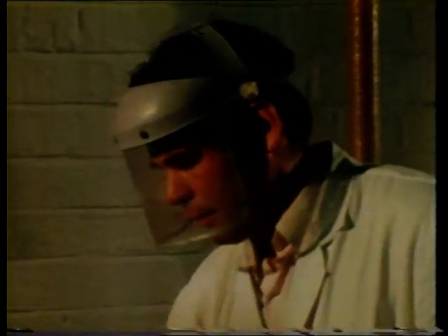First, we put into the molten aluminium a measured quantity of silicon. It's measured out by weight. After time, the silicon will dissolve. Then the magnesium can be added. We don't need anything like as much of this. Like the silicon, magnesium takes time to dissolve. This new material we've formed is called an alloy. It's an alloy of aluminium.